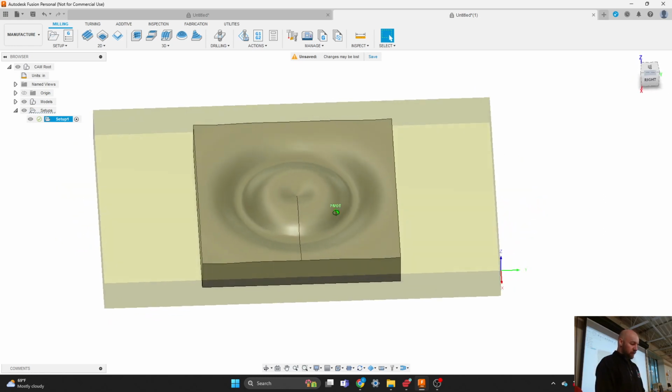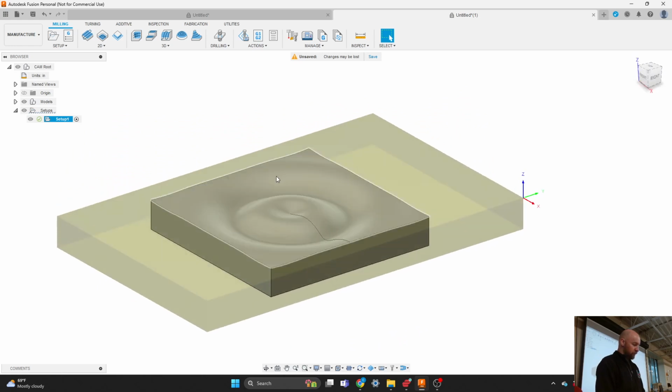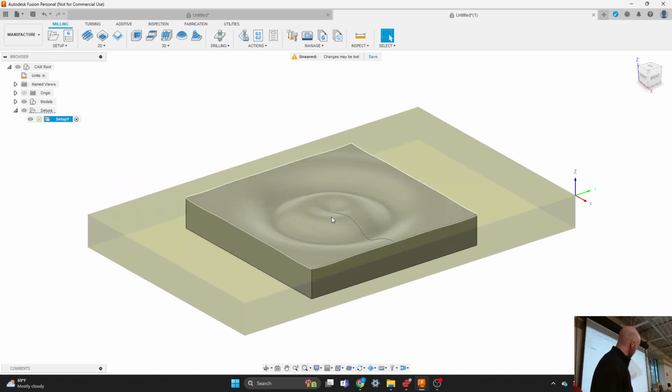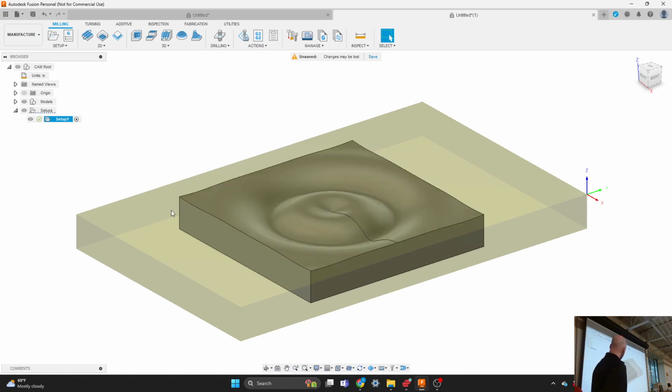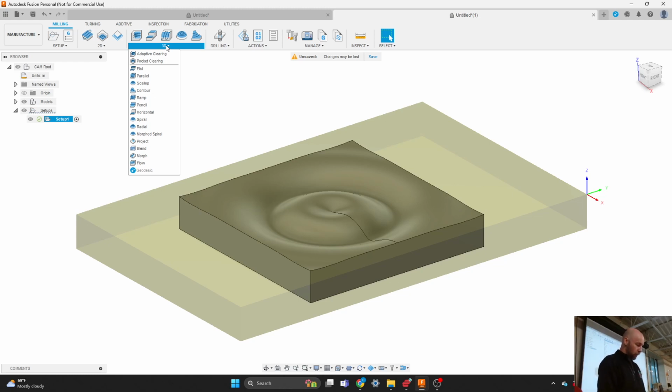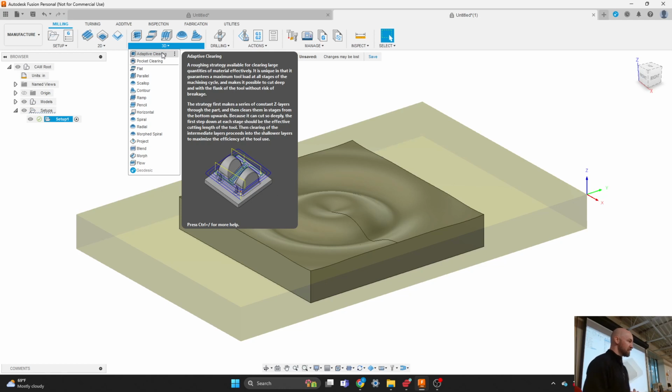Alright, so for a piece of material like there, for an object like this, we probably want to do our contour cutting last. So we want to cut out our object after we do our carving on the top of it here. This carving operation that we're going to do on the top, I think we should probably do in 2 different operations. Why? Because then I can show you 2 different operations. So we could do a roughing pass.